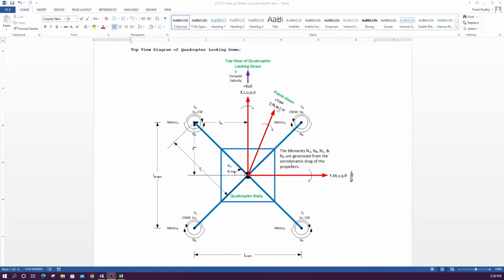W is our vertical velocity, which going down is positive. R is our yaw rate, again turning right is positive. And psi is our azimuth angle, which represents the heading of the aircraft. Again, right is this way. So we are trying to get familiar with some of the parameters in our airframe model.